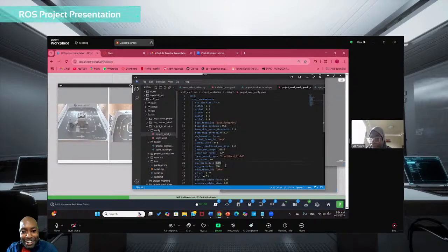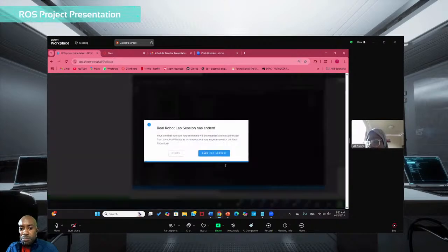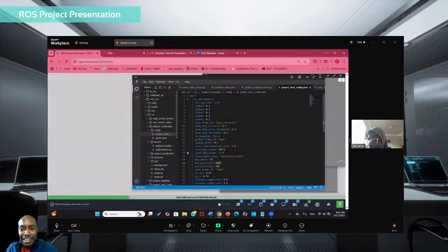Okay, I think you're on the right path. The relevance of the particles is they are like sampling points. So the more samples you take, the more accurate your localization algorithm gets. If you give your AMCL more sample particles, it's going to be more accurate on figuring out where exactly the robot is. So you are on the right path. It's just that some details were not quite in place. But well done for trying to explain it.